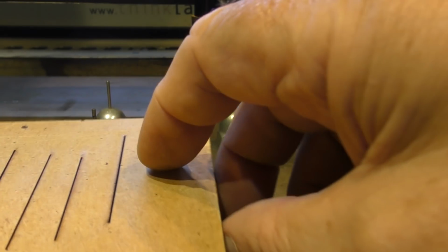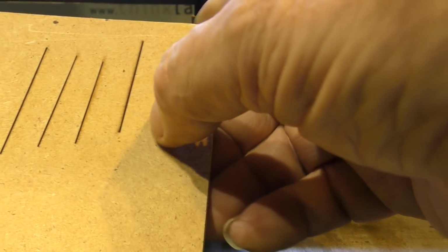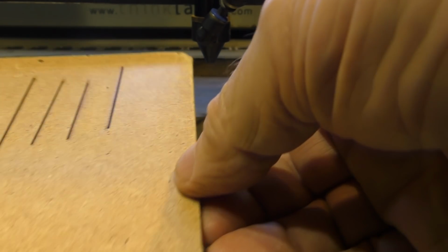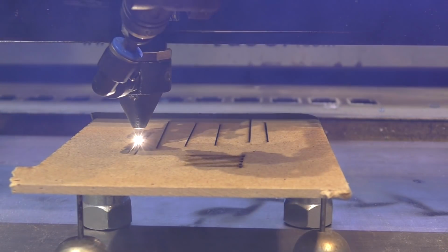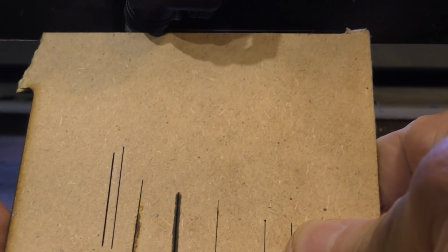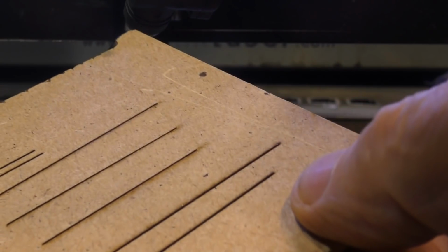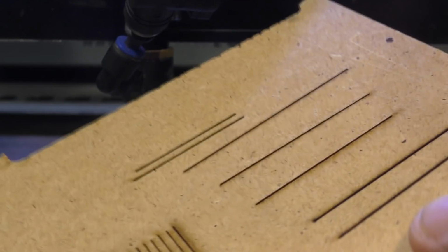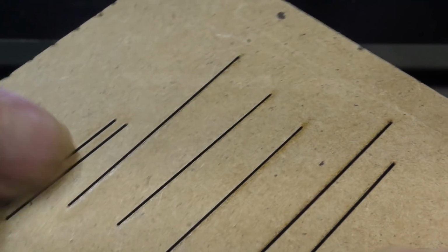And I say most of the air because look, again, we've got a much smaller cut on the back than we have on the top. And that means I've got a tapered cut and I'm choking the airflow through the cut. So I'm running too fast. It's getting better, as you can see. We've got a much wider cut at the bottom now. And again, I've got a lovely clean mark-free cut on the top.